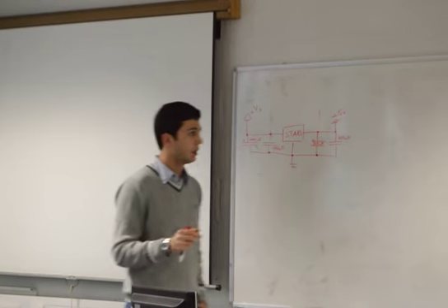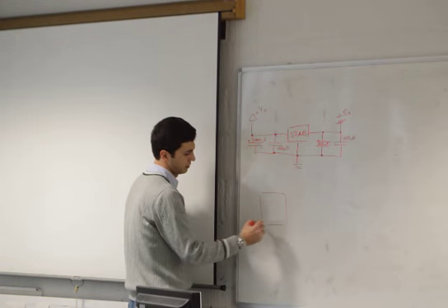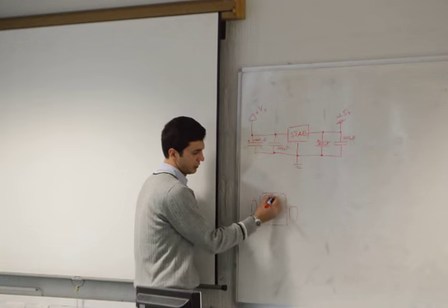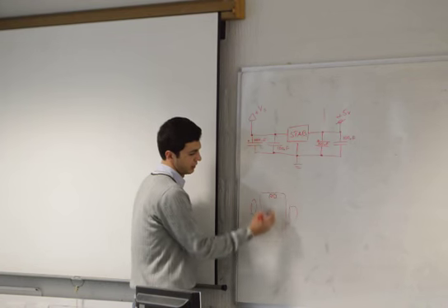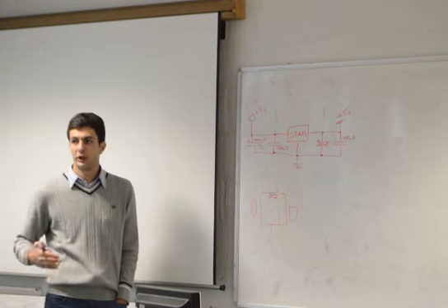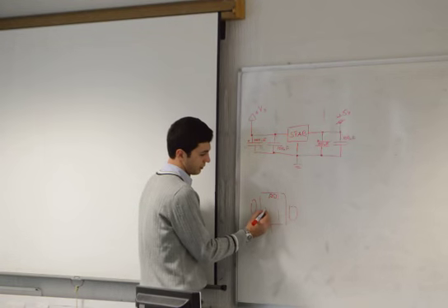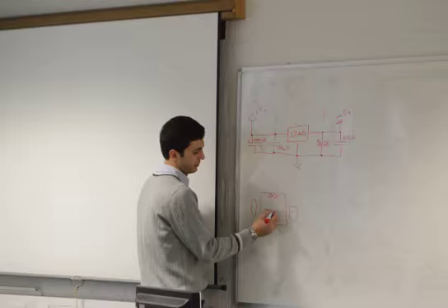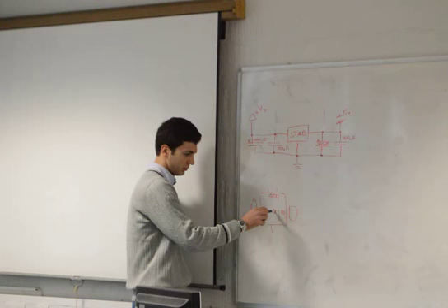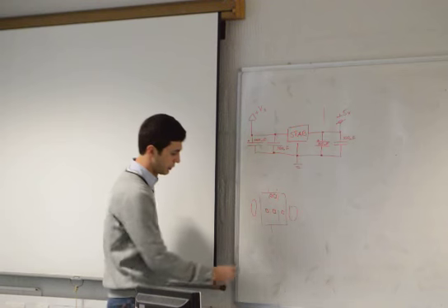Probably. Alright. In that case, I would build the robot in a way. Let's say this is a robot. These are the wheels. I would put two sensors in the front. So this is the line. The sensors will be like this. And because I want the robot to rotate on the 90-degree turn, I will put 4 sensors or maybe 3 sensors here. I'll tell you why. Because the axis on which it's going to rotate is this.